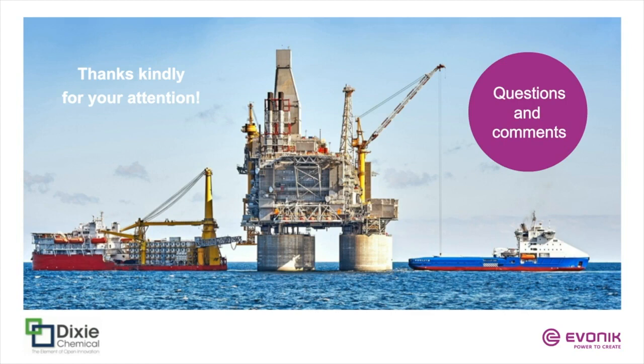first indicator. The second one, which we presented today, is compressive strength, and that can be interpreted a number of different ways. A straight compressive strength, as you saw in the data, we got a very nice progression as we change the blend of the curative, and that will translate directly into hydrostatic crush strength, or at least you can make a correlation as such, so that as you're contemplating the use of and trying to simulate the performance of these epoxy syntactic foams at deeper ocean depths, you can gain an appreciation for a higher compressive strength being able to provide you with a better hydrostatic resistance at the greater ocean depths.